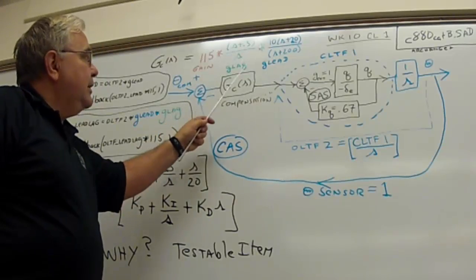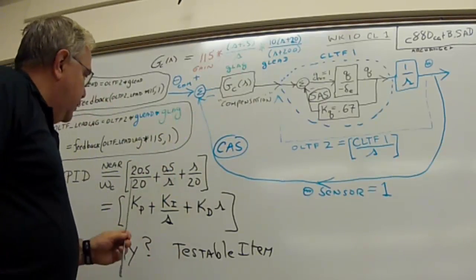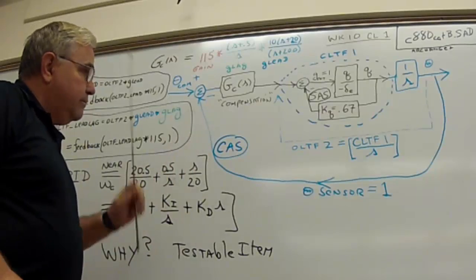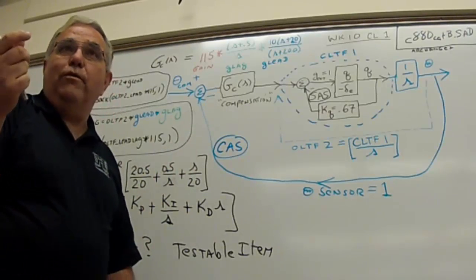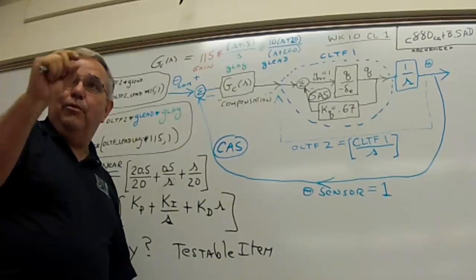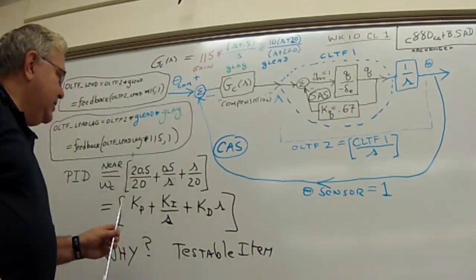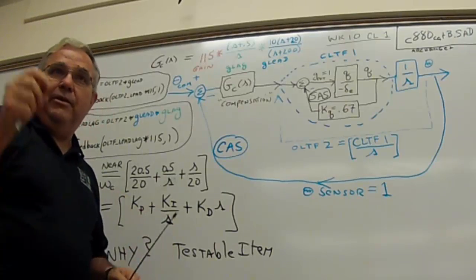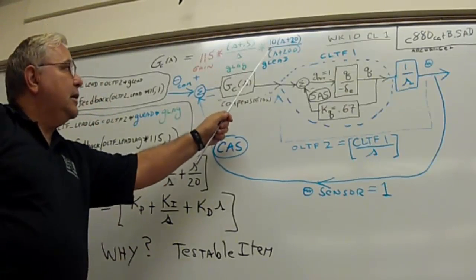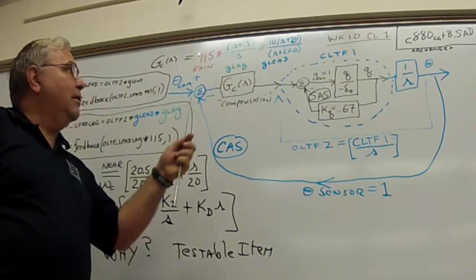And we're going to do an input Q feedback through a gain of 0.67 on MATLAB. That'll be our SAS. And then we will close the outer loop through theta and put the compensator in the forward loop for the second loop closure.